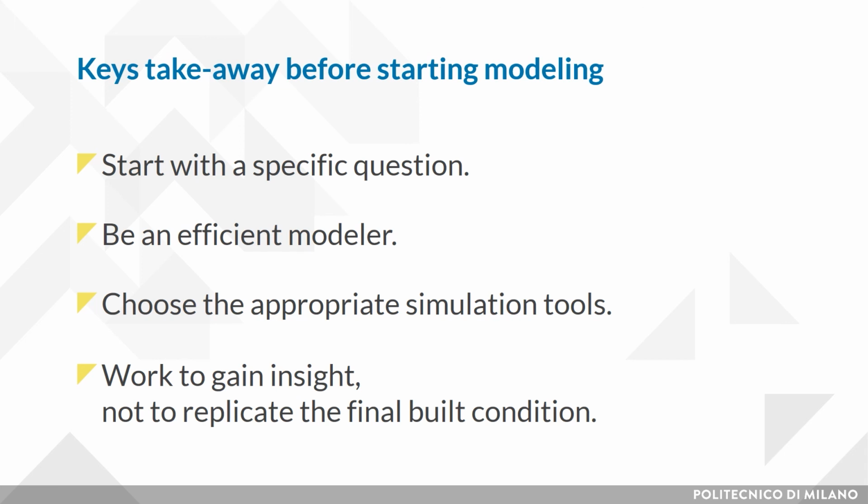If you start with a specific question like this, the analysis will be more manageable than if you try to deliver high performance all at once. Second, be an efficient modeler. You don't have to model everything to answer a specific question. Often, building a quick study model off to the side of a representative floor or a typical condition, for example, is a fast and easy way to inform the refinement of your design.